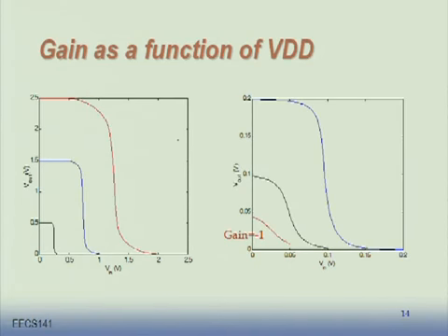Did you listen to what I said 3 minutes ago? Part of it is a component here of longer channel devices, but particularly in short channel devices, your DIBL is suppressed at low voltages. You're not exercising the DIBL of the device, so it's good. And then eventually, it gets pretty good. But when you drop it to a really low supply voltage, 0.2 volts, the inverter still looks okay.